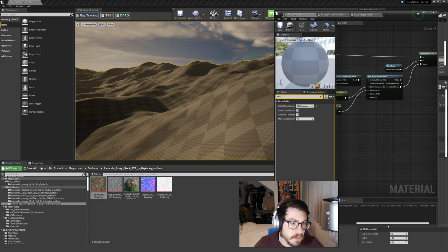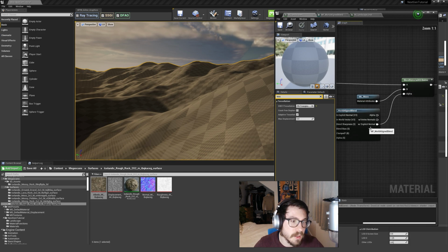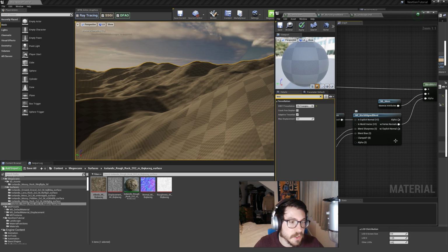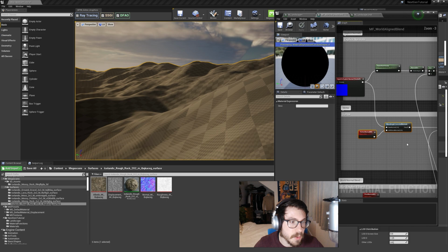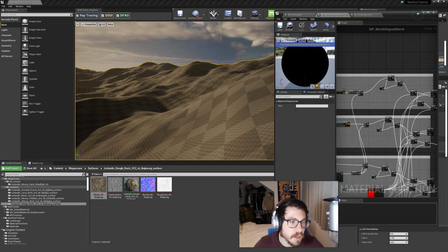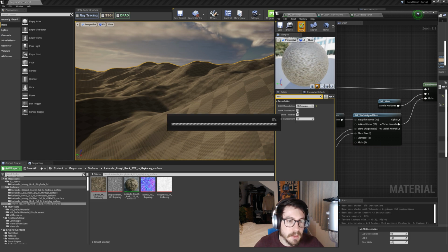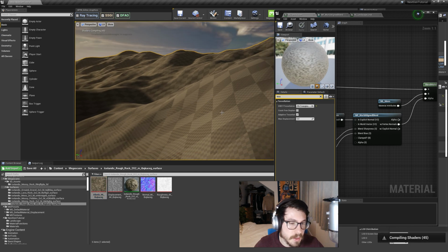It tells us that invert node used in the vertex domain shader input, which is because we connected the explicit normals, but of course this is exactly the issue I talked about earlier that doesn't work. So we need to use the new vertex normals. As in our material function, you remember we connected this to the second vertex blend here and not to the explicit normals, right? So we use the vertex normal, then this error goes away with the tessellation, and then it should tessellate correctly and apply the displacement as well.